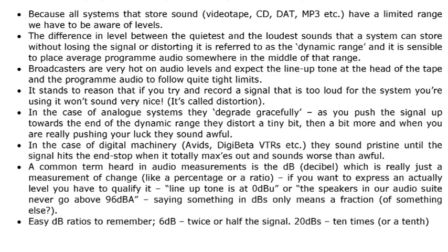It sounds a bit wrong, but not horrible. Whereas with digital machinery, like an Avid or a Digibeta or a VTR or any other kind of digital system you might care to name, when your sound is too loud and it hits that end stop, it sounds awful. It sounds worse than awful. The system can't accommodate the level, and it clips, and it just sounds terrible.